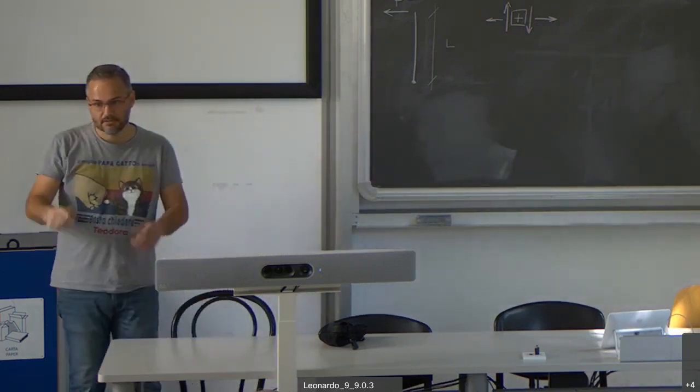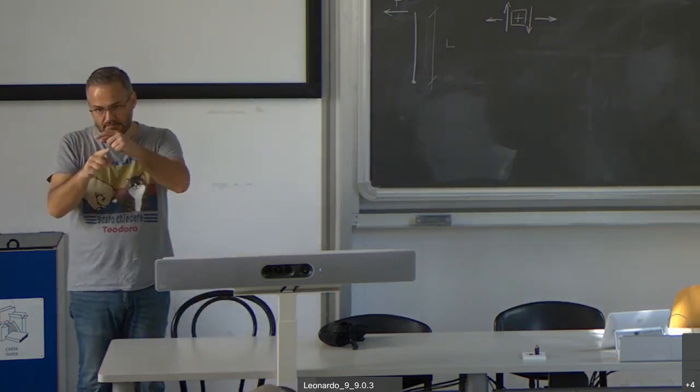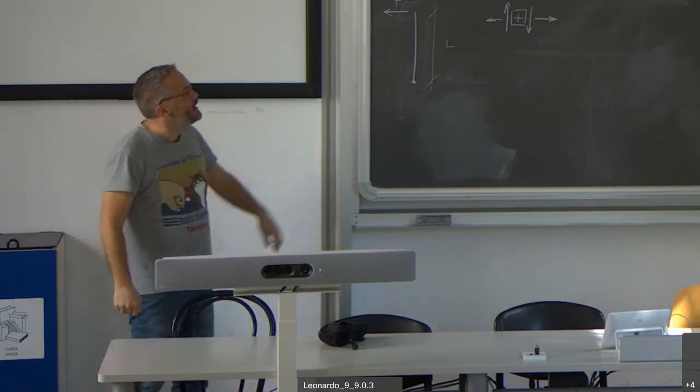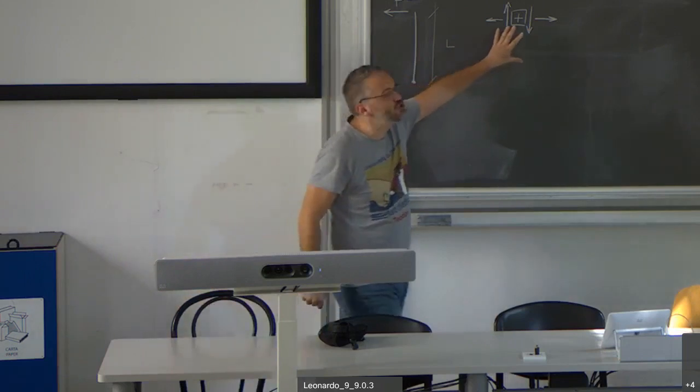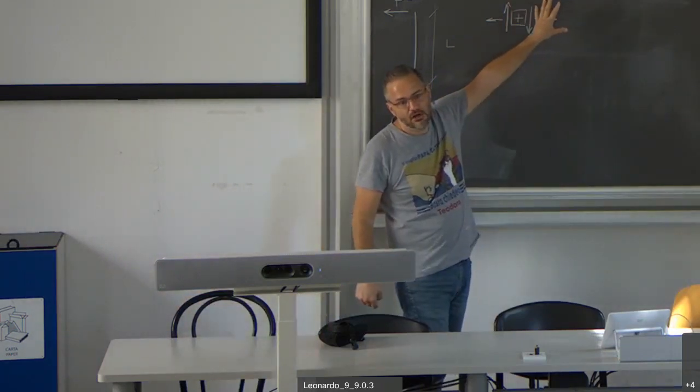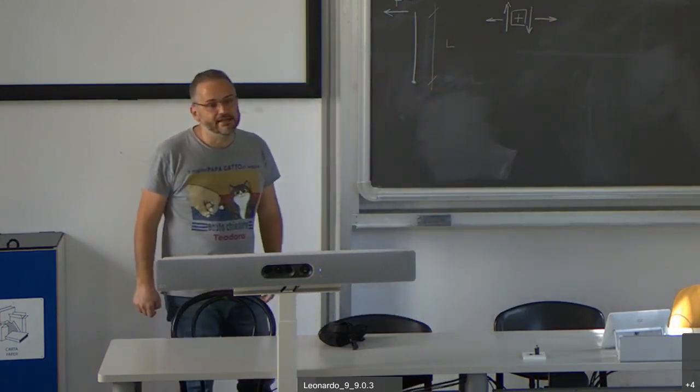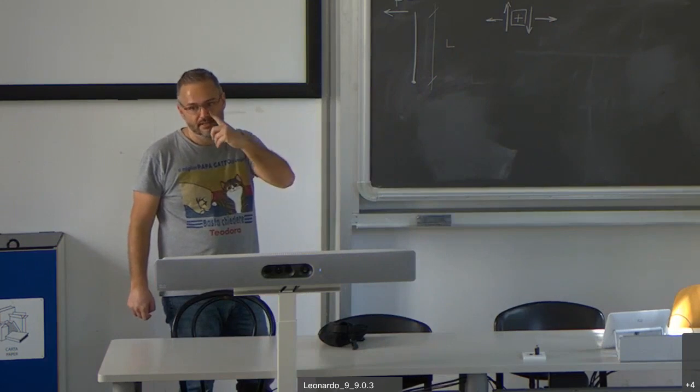You see it? The member rotates clockwise. Tension means it's pulled, it will elongate. As for the bending moment diagram, I don't need to place anything because I will plot it one way or the other and then look where the tension side is, okay?